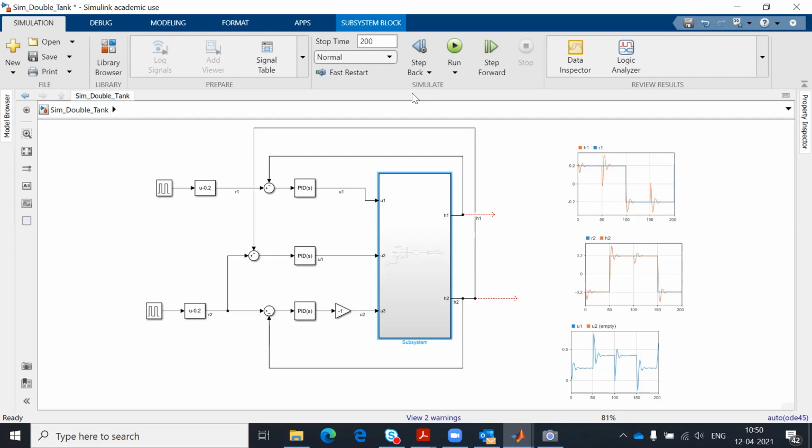For example, you have a PI controller, but the parameters of the PI controller can change along the way. So when you change the load, let's say you have a mechanism to find if the load has changed, and now you can retune or fine tune the parameters of the controller online. We have such a controller, and by the way, it doesn't have to be a PI.